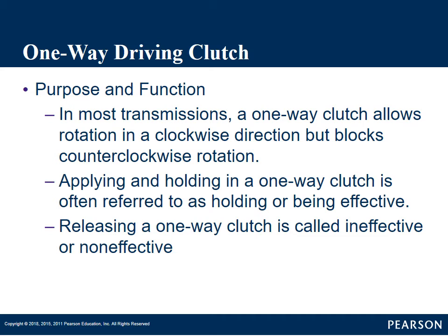When we're talking about one-way clutch packs, applying and holding in a one-way clutch is referred to as holding or being effective. So when they lock a one-way clutch, when they hold it with maybe a clutch pack, they're saying, and we'll see this when we're looking at clutch and band apply charts, that one-way clutch is being effective. If it's released and is allowed to freewheel, it is being called ineffective or non-effective. That's important to know when we're looking at clutches and band charts.